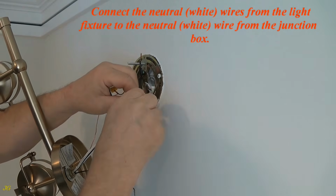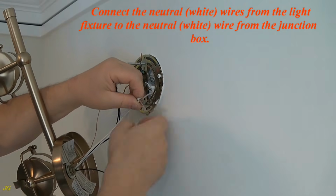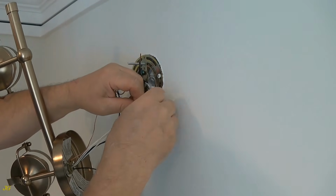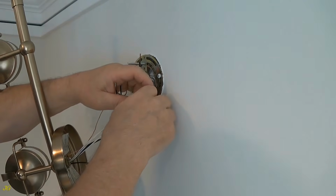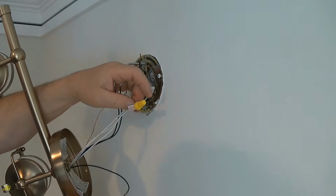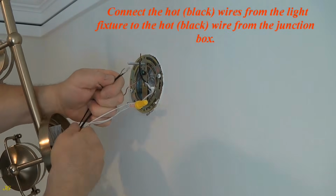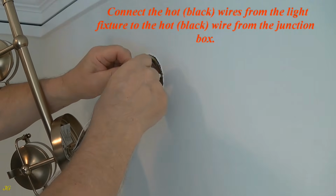Connect the neutral, white, wires from the light fixture to the neutral, white, wire from the junction box. Connect the hot, black, wires from the light fixture to the hot, black, wire from the junction box.